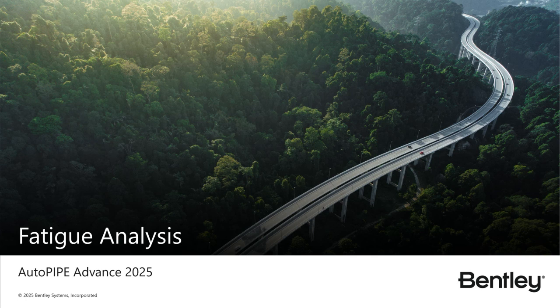Fatigue analysis is a special type of damage that we see in these piping systems that can really restrict the life of the plant. With fatigue, we're looking at loads that are applied and taken off that are within the scope of the project, but that repeated loading can cause lots of damage, eventually critical failure.